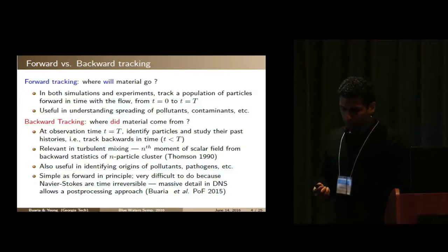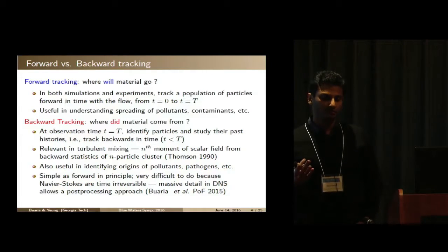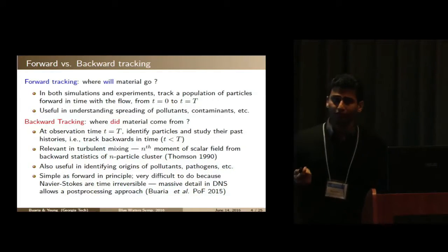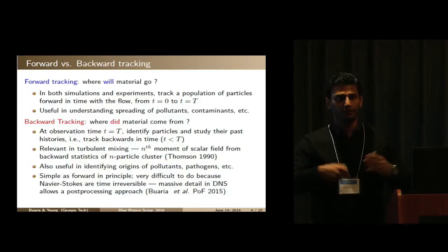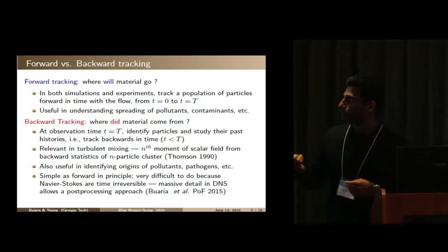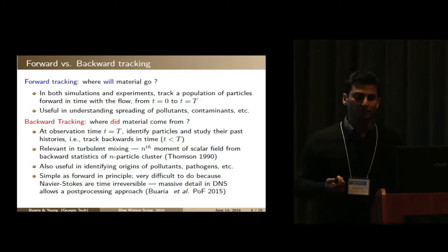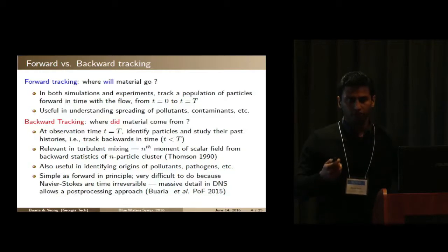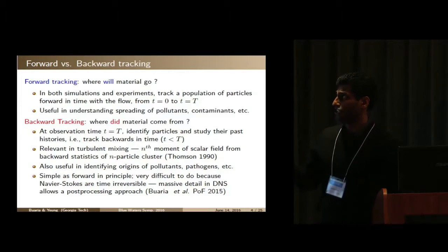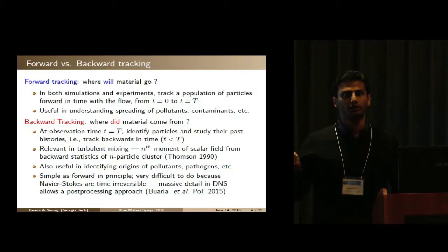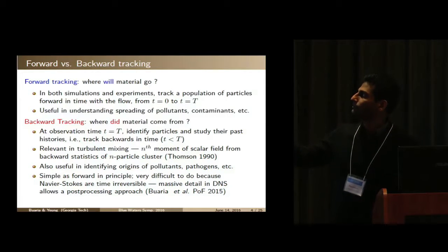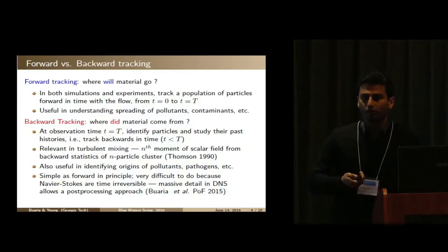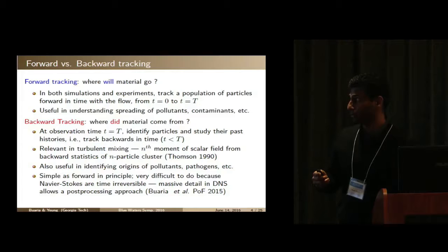When we talk about turbulent dispersion, there are two aspects from which we can look at it. One is, we ask ourselves, given this material, how will it spread? That's the most common approach studied in both experiments and simulations, where we introduce some set of particles at some initial time t equal to 0, and then track them forward with the flow velocity to some final observation time t equal to capital T. And this obviously is very helpful in understanding the spread of anything in turbulent fluids.